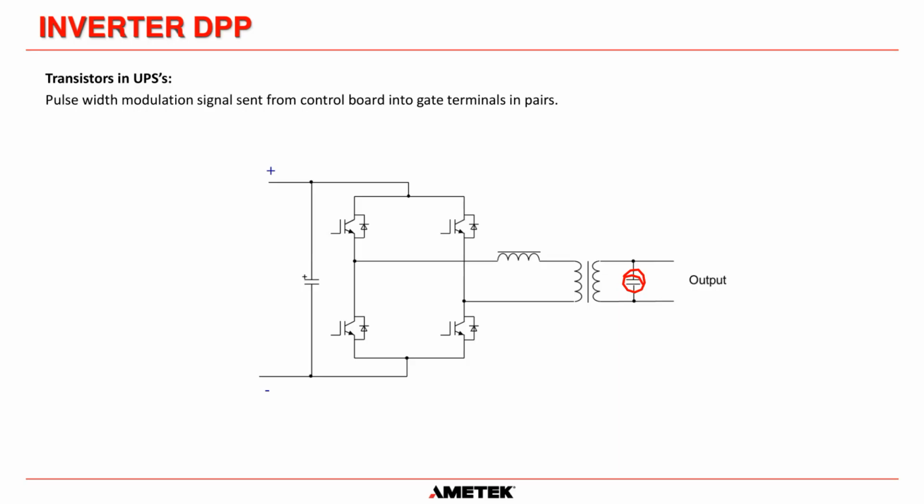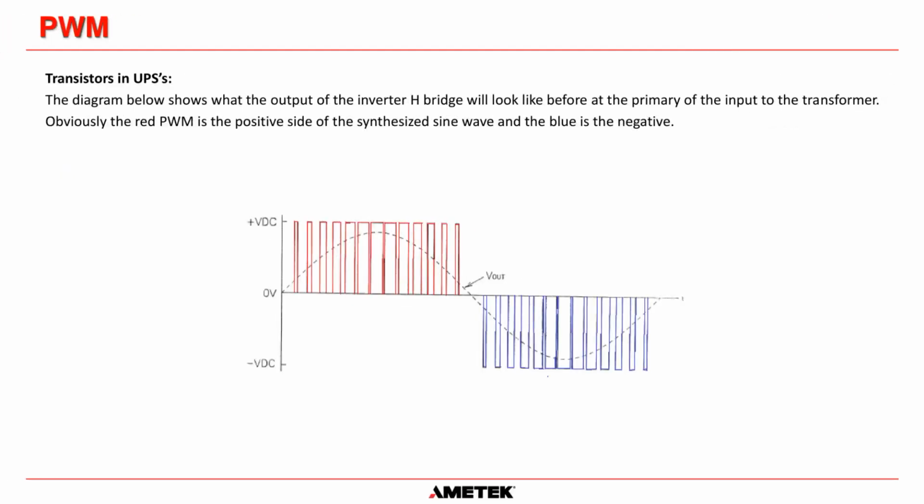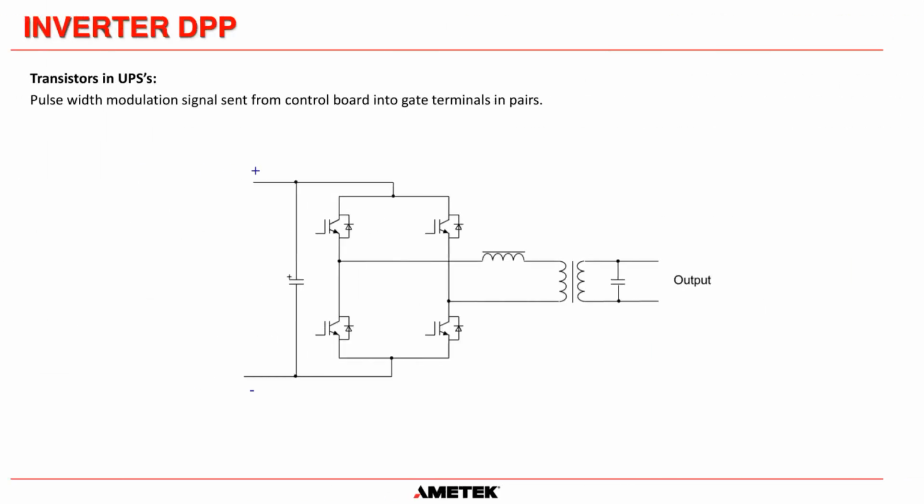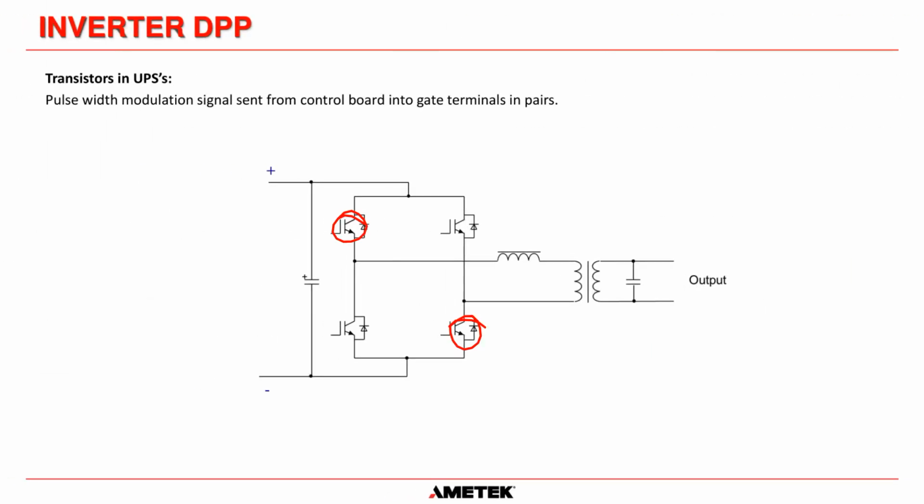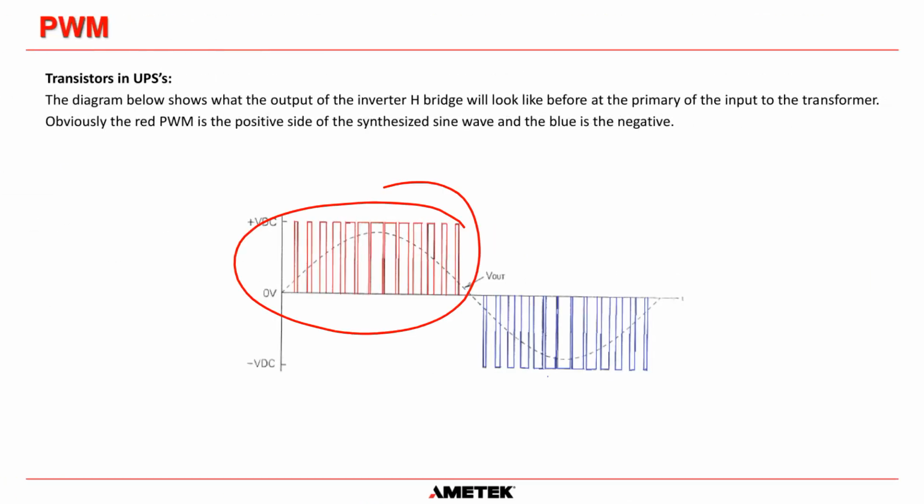So there is our capacitor there, and there is our transformer, which has inductance. We used to have a separate inductor to work. It was an LC circuit, an inductor capacitor circuit, but now we've put the inductor inside the transformer to get rid of this component here, just for ease, okay? And what we're doing is we're creating a PWM signal, okay? So what we're doing is we're switching these two transistors on and create this to give this. And once again, this is not 8 kilohertz.